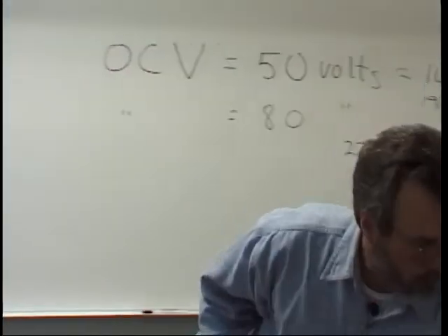When frost appears, the small amount of moisture in the gas can form ice in the regulator and either stop the flow entirely or break off and be blown into the weld. In either case, porosity can and usually does result. So if you're out there welding and you're getting frost on the regulator, you've got to be aware of that.